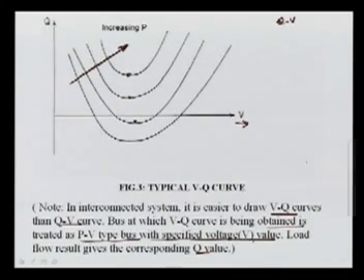Then you can get the voltage for different P and Q. So for any bus you can get V and Q for various load increases, draw a curve and find this Q. This also gives information about your system stability, and these here are the nose points.